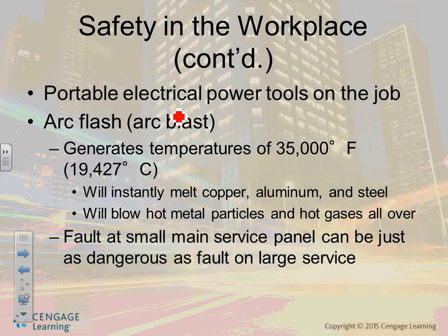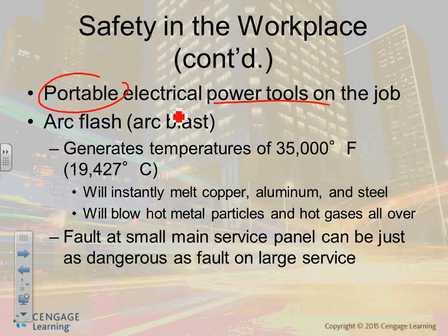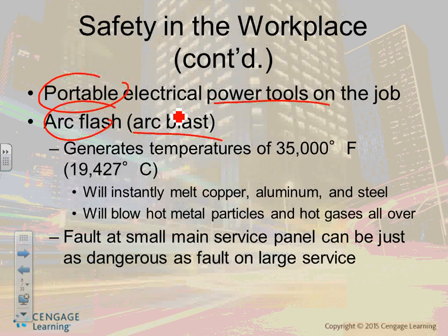A part of the safety training, guys, is when you have portable tools, and we talked about this one, power tools and what's not, they have to be plugged into GFCI. We all know that, on a construction site, anywhere, portable tools. Safety is also related to arc flash as well as arc blast. Arc flash is a big ball of fire. Arc blast is all the melted cover that runs at you as an effect of the rate of arc heat.